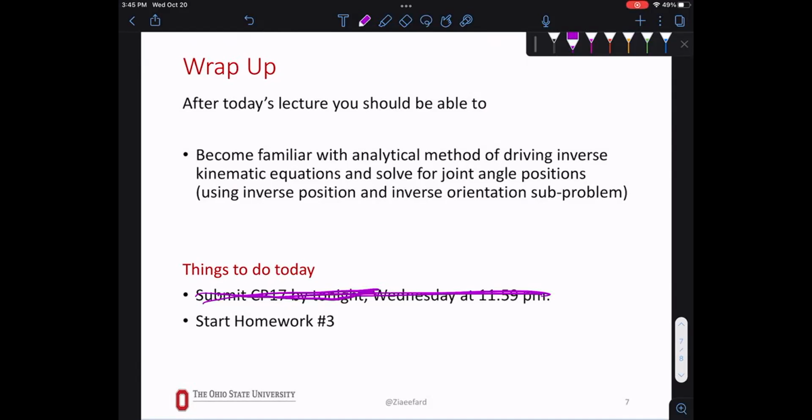So think about these forces and moments: how do they show their effect on the robot? If there's a force, there's going to be a torque created on the joints. Why is this important? Your joints are made of DC motors or some sort of actuator, so you have to consider these forces when you're speccing the motor. When you get to control, you're going to have force control, so you'll think about the effect of these forces and moments on each joint.